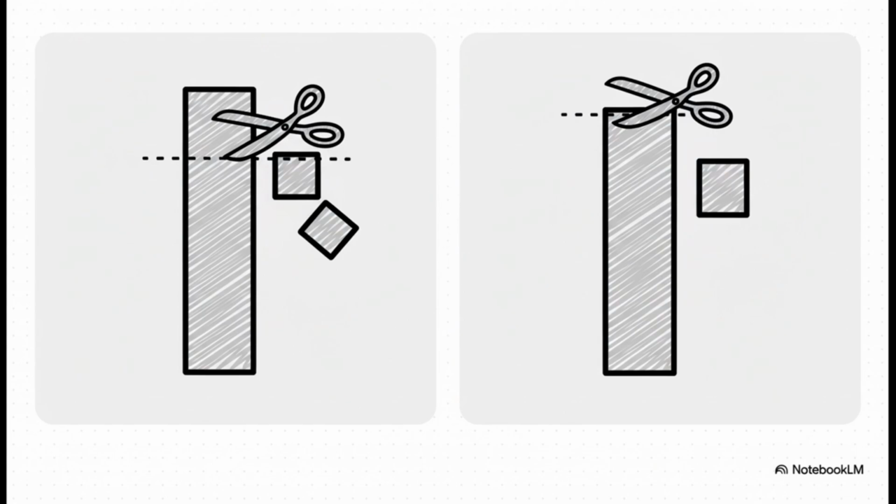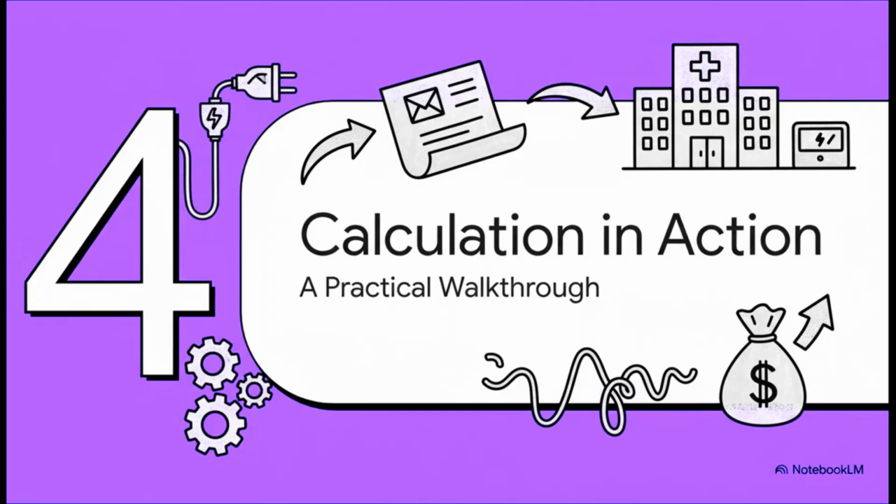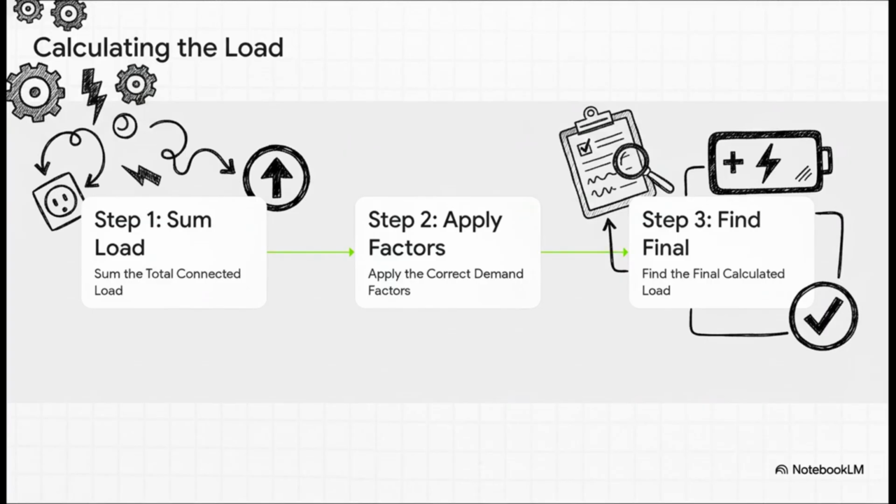But after you pass that 5,000 VA mark, the code starts to acknowledge diversity. The load from 5,001 VA up to 10,000 VA gets a 50% demand factor. So the assumed usage is cut in half for that slice. And then comes the biggest drop, which seems to really define these spaces. Yes. Any remainder over 10,000 VA, the demand factor just plummets. It goes down to 25%. 25%. That's a huge drop.